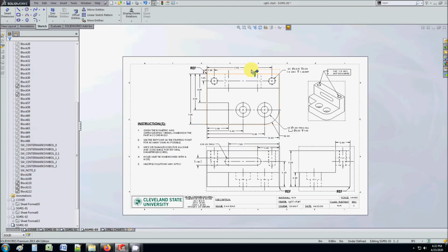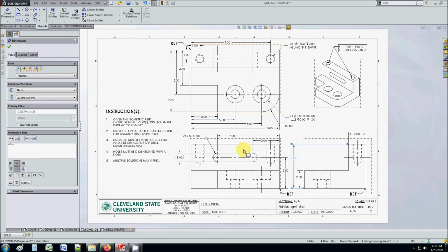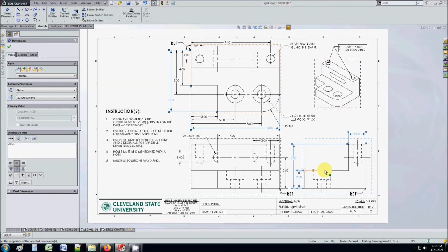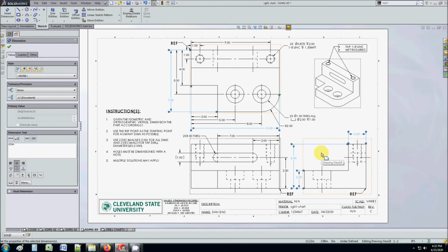But what I want to do now is just make sure that there's no missing dimensions. So again, my strategy for that is to pretend I'm trying to machine this. So I need the length, height, and width, and then I need to cut this end out. So my end mill is going to come out here and cut this off. See what I'm trying to do here? I need to know where each of these coordinates are located. That's what I need to know.